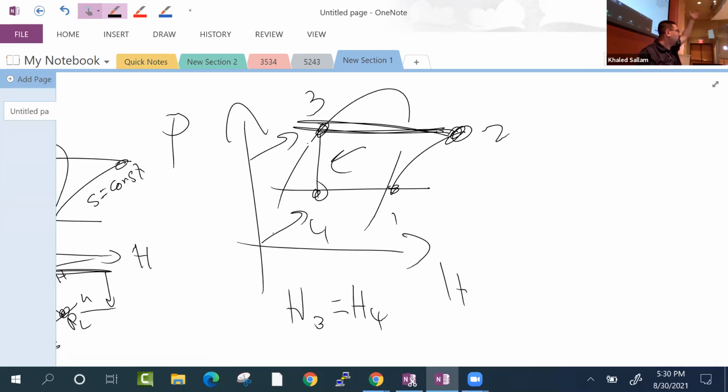But you know, it was so high. And was there any way I can lower its temperature and still get something? What can take you from high temperature and pressure to low temperature and pressure and give you something? Turbine. So a turbine here would be ideal, except what? Why is not everyone using a turbine in this cycle? They are using just a small capillary tube that kills the pressure and takes the temperature down with it. And they call it a day and we are happy.